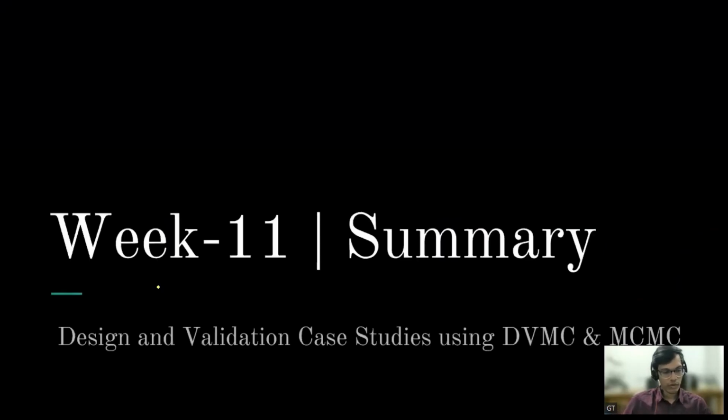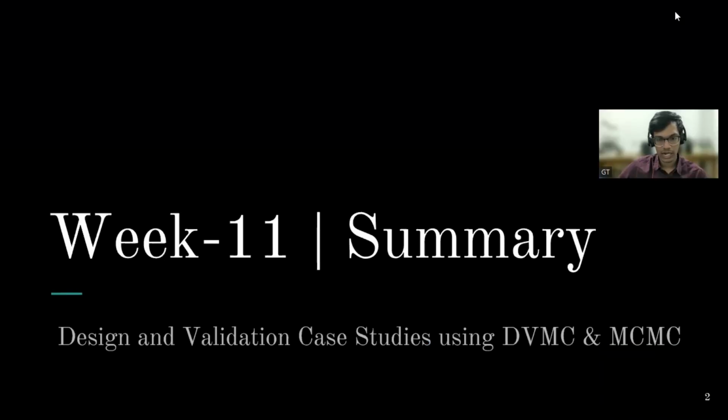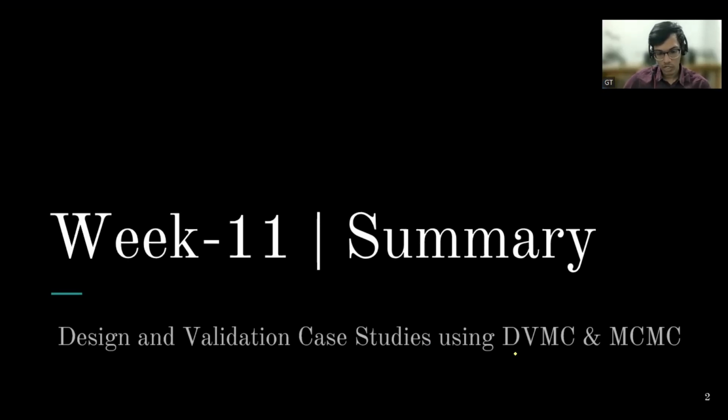Before we go into week 12, let us summarize what we had discussed in the last week, which is week 11. Week 11 is about design and validation case study using digital voltage mode control and mixed current mode control. There was a quick recap of the implementation of digital voltage mode control and mixed signal current mode control. We have seen the Verilog implementation, not the HDL code, but the block diagram. And then we have seen the MATLAB simulation versus hardware results comparison.